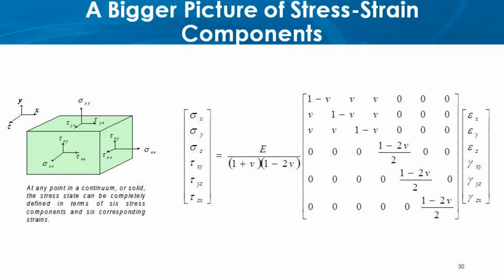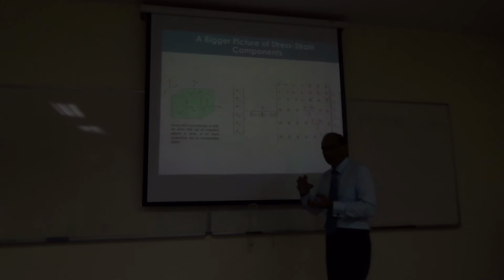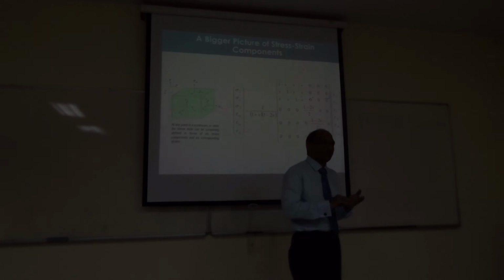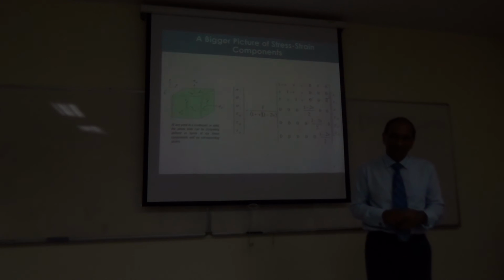So coming back to this, the stress strain curve that I just showed you is not one. In each direction we will have similar curves, right? That means that curve, that property, is not the end of the story, because that is only one direction. Every direction could have a different curve, a different relationship between stress and strain in that direction. Some brittle, some not brittle. Same material, in a certain direction it will be brittle, in some direction it will not be brittle. In some direction it will be cyclic very good, in some direction it will not be good. So the same material can exhibit linear, inelastic, nonlinear properties within that material depending upon the direction of loading, right?